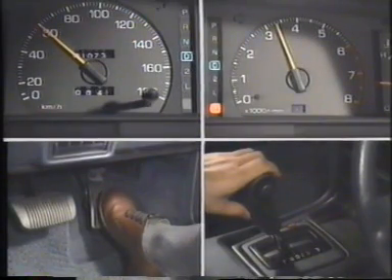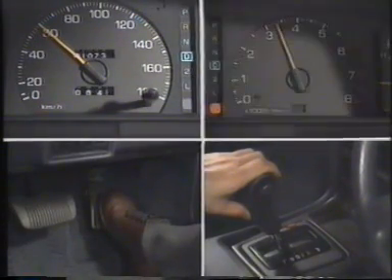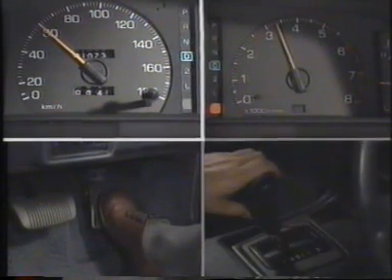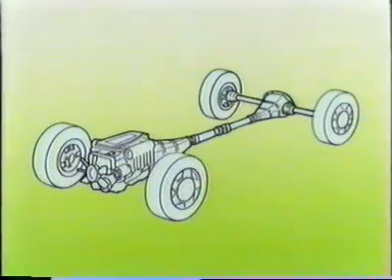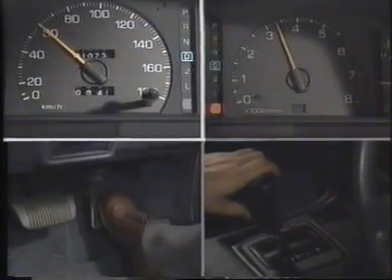Now, let's summarize all the test results. The test results indicate that the engine load and the engine speed are not related to the problem. The shift lever position is also unrelated to the problem. You can now conclude that the vibration is not caused by the engine or the transmission. So we need to look for some other factors.